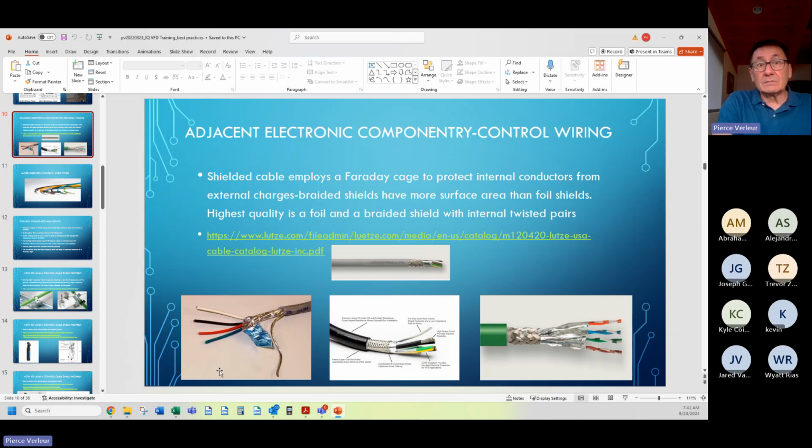What is VFD output? It's high frequency noise. So having both gives you a broader range of frequencies that you can effectively sink to ground on a low impedance path. You want all that noise to go to ground. You don't want it to go affect other parts of your system.